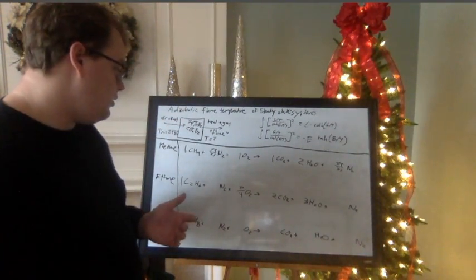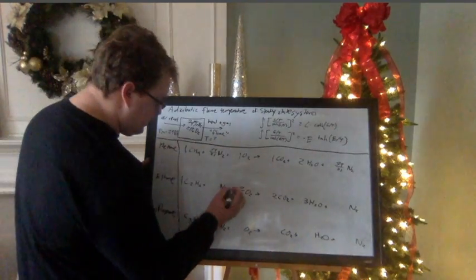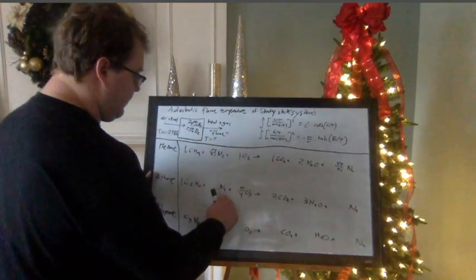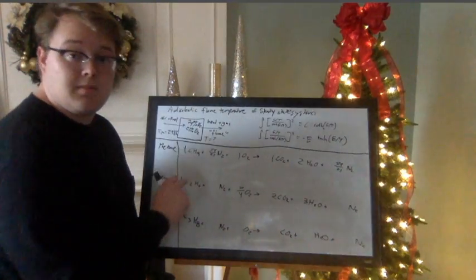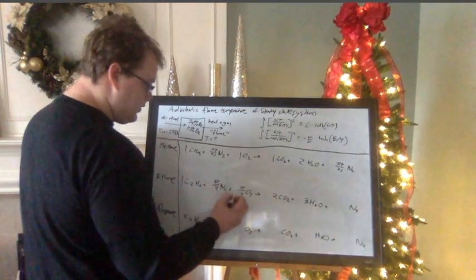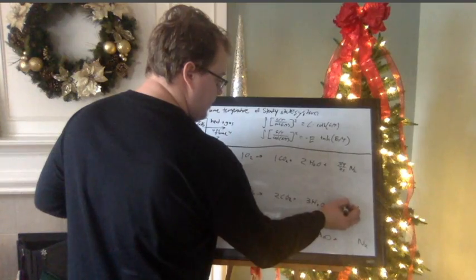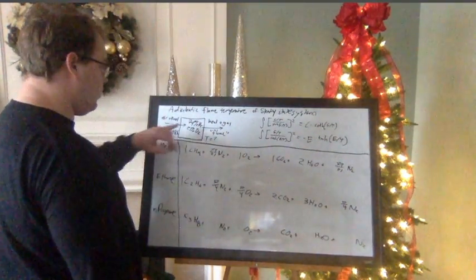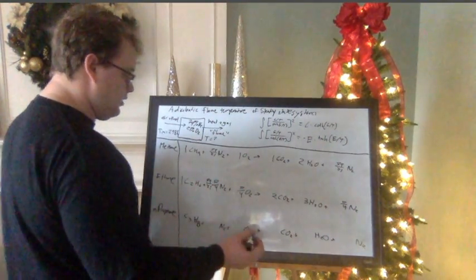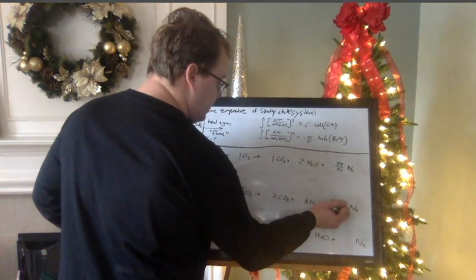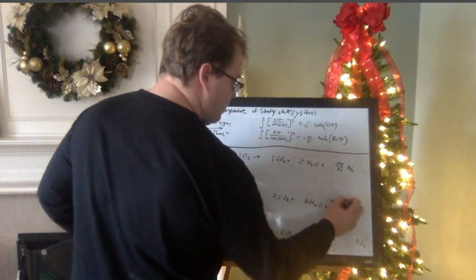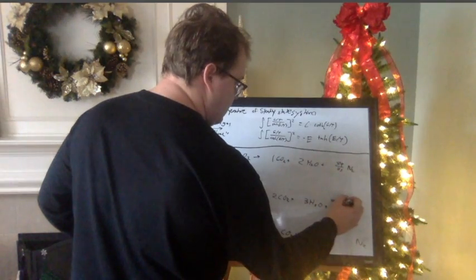So I need to take that into consideration. If I multiply my oxygen by 7 over 4, and I need to have this relationship between my nitrogen and my oxygen, I need to multiply nitrogen by 7 over 4 as well. So 7 over 4 nitrogen, 7 over 4 nitrogen, and then of course my 79 over 21. So 79 over 21 times 7 over 4 nitrogen, and then 79 over 21 times my 7 over 4 nitrogen on my right side. I cannot draw my 7s. There we go.